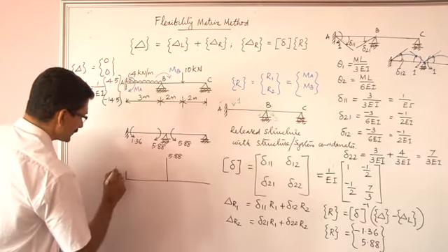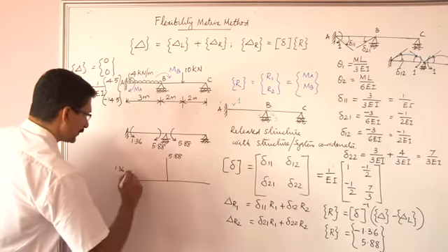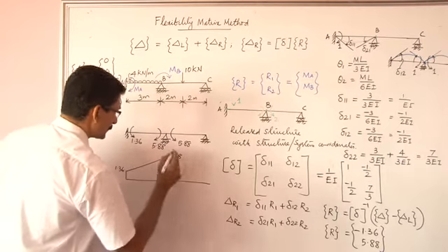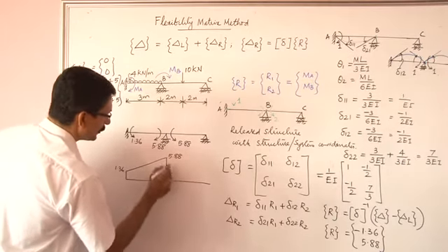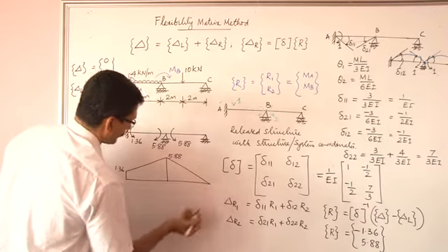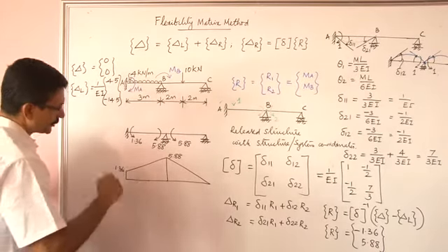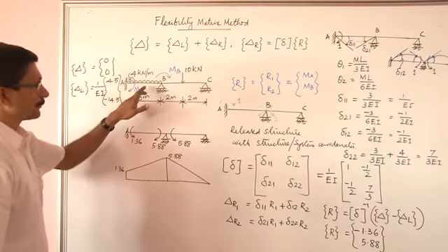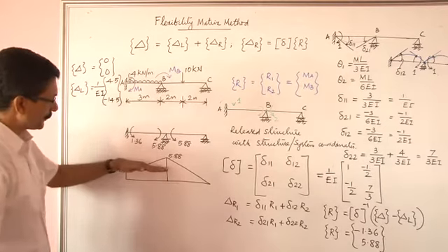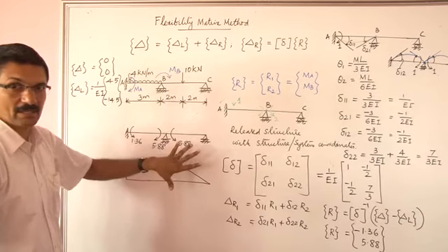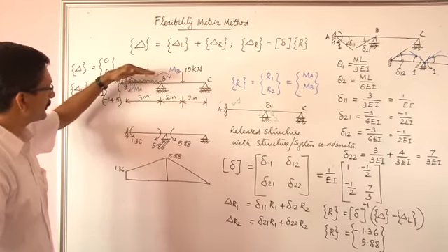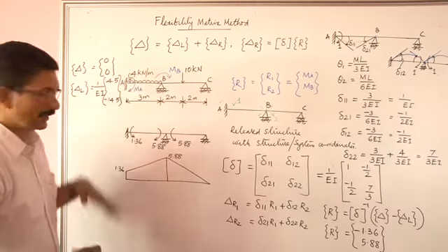This is 1.36. We can connect them together. The moment here is 0. Now above this is a support moment diagram. Above this we can superimpose the simply supported bending moment diagram. Now the support moment diagram is going to be hogging in nature, and the simply supported bending moment diagram is going to be sagging in nature.